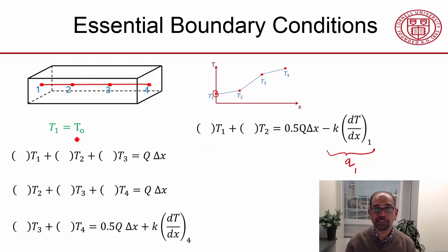It's essential for it, which is why this is known as an essential boundary condition. That's the terminology, and contrast it to the flux boundary condition here, where you can't say that the shape has to essentially satisfy that. In fact, we'll see that the shape won't satisfy the natural or the flux boundary condition.